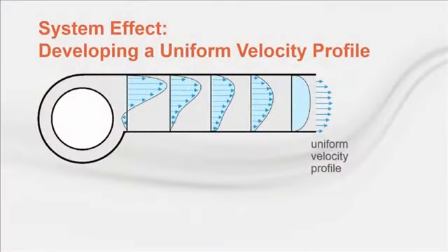Turbulence caused by airflow restriction at either the fan inlet or outlet, or non-uniform air distribution, can negatively impact the performance of a fan when it's installed in an air handling unit or connected to a duct system. This is commonly called system effect. System effect prevents the fan from operating as it did under laboratory rating conditions.